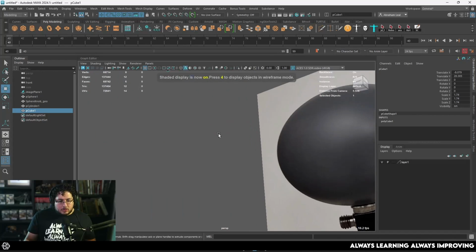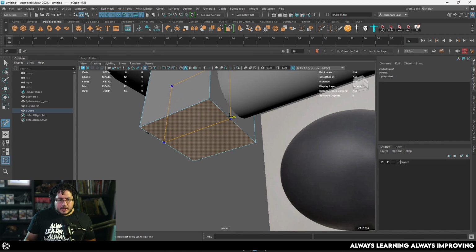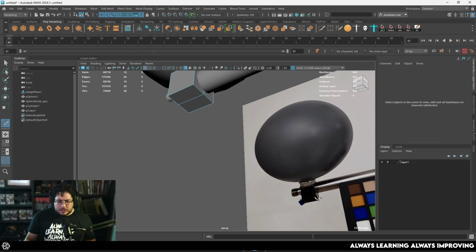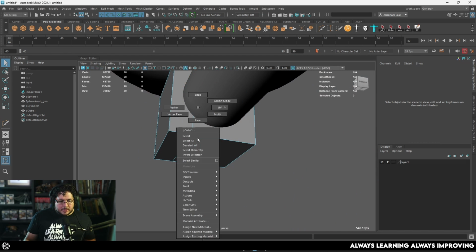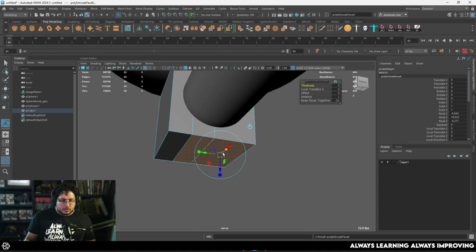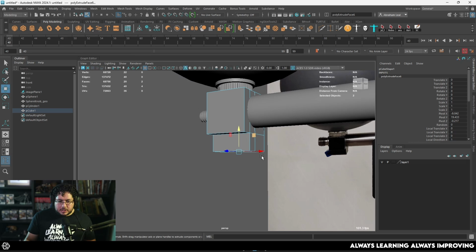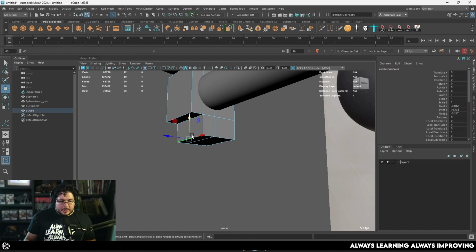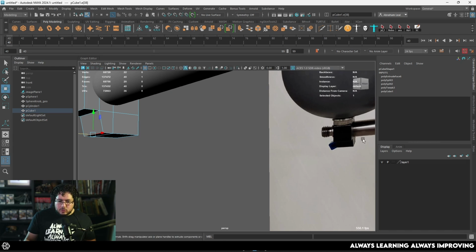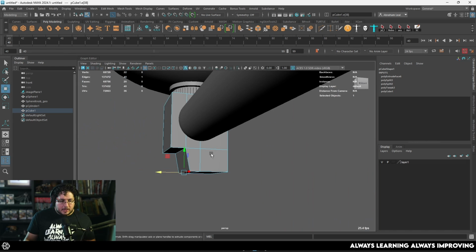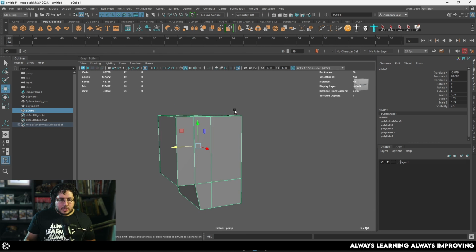I'm going to go to the lower section. I'm going to grab this face, or actually I'm going to assign one line at the very center, because you can see that there's a little bit of a cut right around there. So I'm going to grab this too, Control E, and push them down. It's going to give me this sort of block effect. Then I can see a little bit of an angle of this thing pushing back. Now I do like this section that we see there on the line, and let me show you how I would do a square right there.